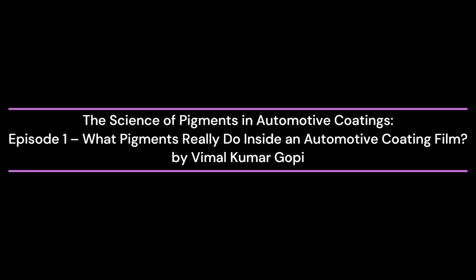Black pigments, particularly carbon black, rely primarily on absorption across a broad range of wavelengths. This results in deep black coloration and strong UV absorption. While this UV absorption can protect underlying layers, it also leads to heat buildup, which must be considered in automotive applications where thermal stability and dimensional control are important.